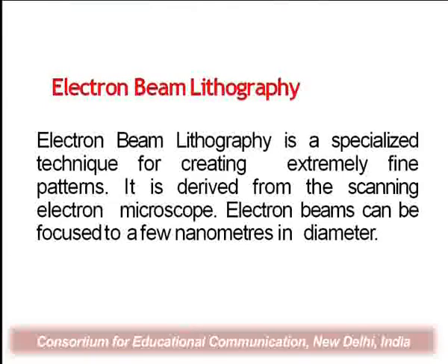The next important lithography method is electron beam lithography. As the name indicates, we require an electron beam that can be focused to a nanometer diameter, so that we can develop nano devices by using electron beam lithography. So what is electron beam lithography? It is a specialized technique for creating extremely fine patterns by using exposure to an electron beam.